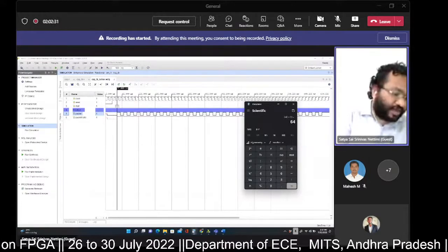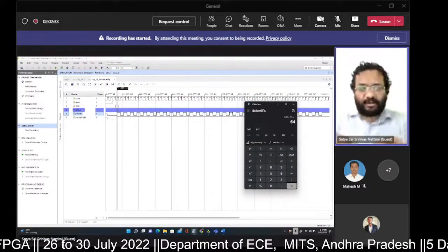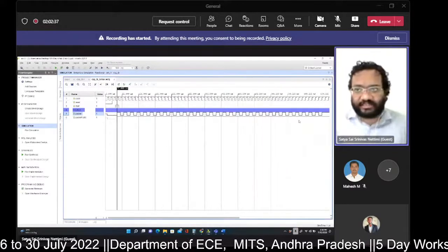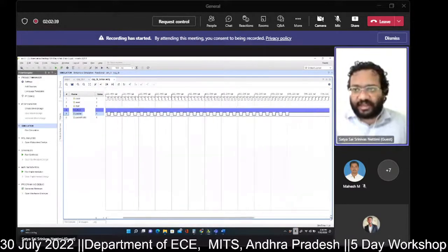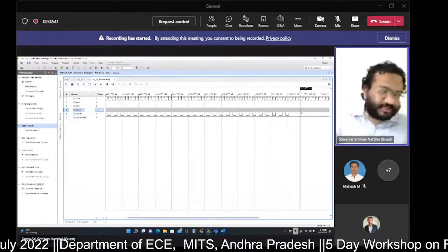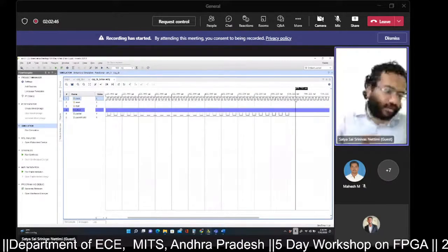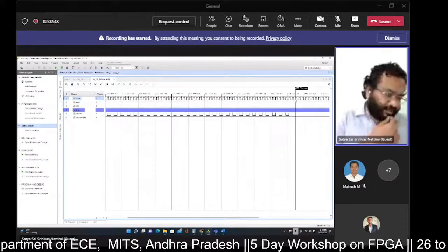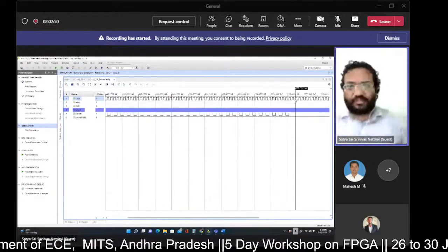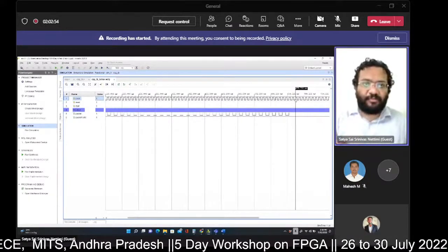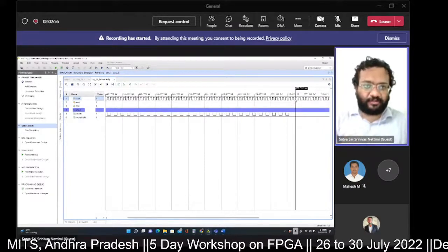That means from the marker starting at 35 nanoseconds to the marker ending at 675 nanoseconds, in between these two markers we have 64 clock cycles. That means in each clock cycle we are outputting 1 bit of the Ethernet packet.